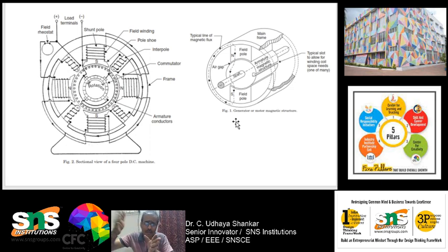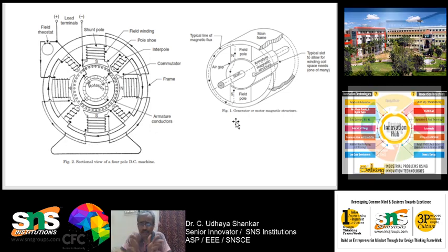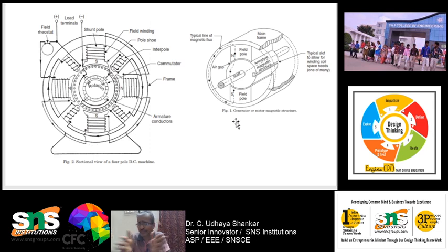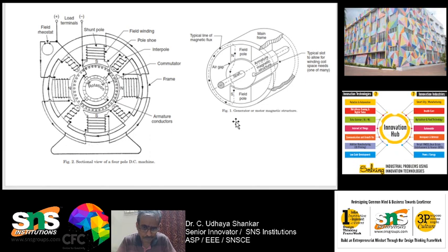It is a combination of many steel structures with insulating mica in between, and then it will be stacked with the help of bolts and nuts, and made as a single core. By doing so, the eddy current losses will be reduced. Since the eddy current losses are reduced, the efficiency will be good because of less power loss. The laminations will be only about 0.5 mm thick.